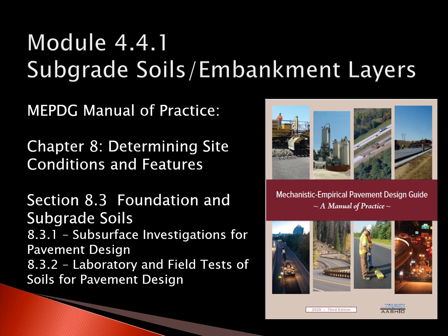Chapter 8 of the MEPDG Manual of Practice provides discussion on determining the site condition and features. Section 8.3 of Chapter 8 of the Manual of Practice includes suggestions for the subsurface investigation and laboratory and field test of soils for pavement design.